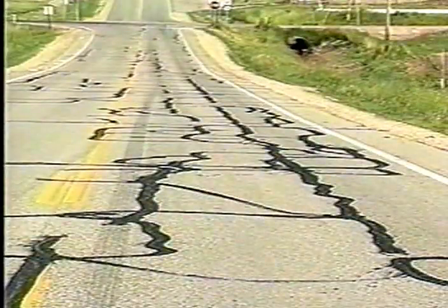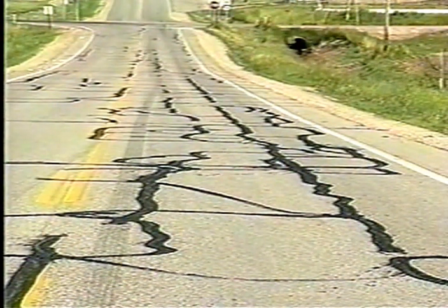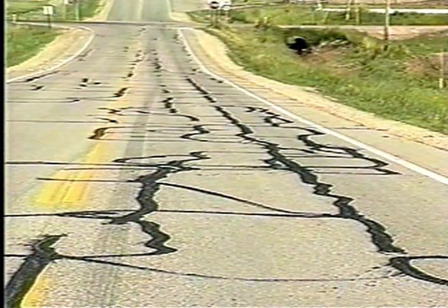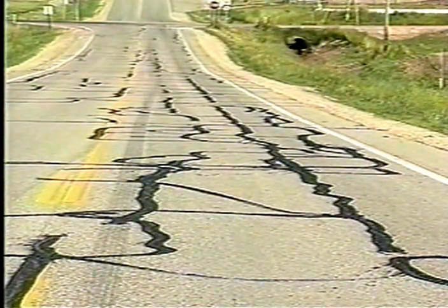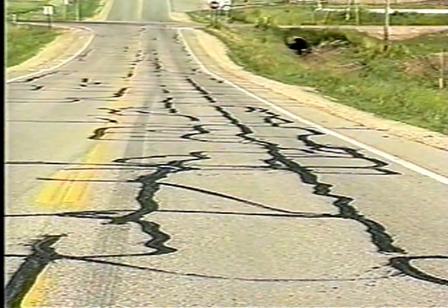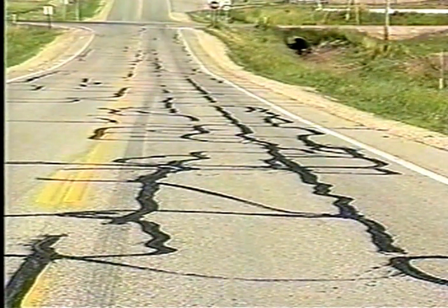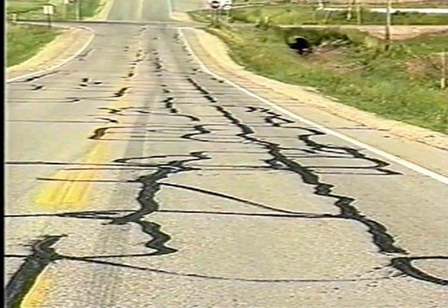So it really points out the need to know more about the pavements underneath as you're interpreting crack patterns just in the surface. For example, if we take a look at this field video, you can see an area where you have a lot of reflective cracking. This is a fairly new asphalt pavement, and they have had to do extensive crack sealing. That's probably because they had more deterioration under there and simply covered it up with an asphalt overlay rather than doing a more extensive recycling or patching. So here you have extensive cracks reflected through a new surface.